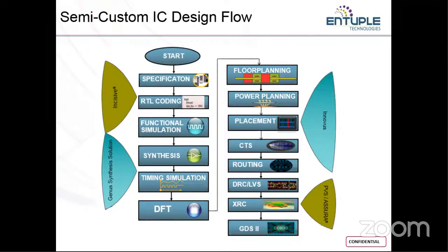What are the gate to gate delays, the net to net delays, the input to output delays, the propagation delay, whether it is rise time or fall time, what is the slack involved in the design, what is the slew involved in the design. All these things can be checked.